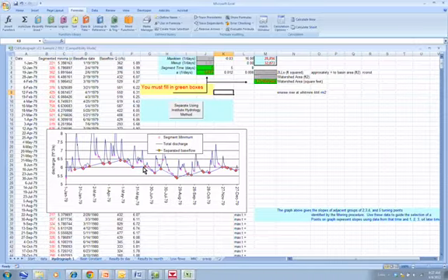That's one approach, but another valid assumption would be that the recharge is really associated with this pulse and rainfall, that the rainfall goes up and that pushes some of the water down and gets it into the aquifer. So rather than being uniformly distributed between the turning points, it's really more of a pulse, perhaps associated with this peak flow.